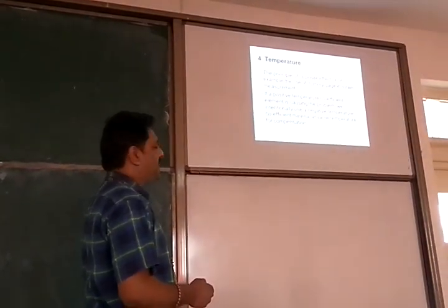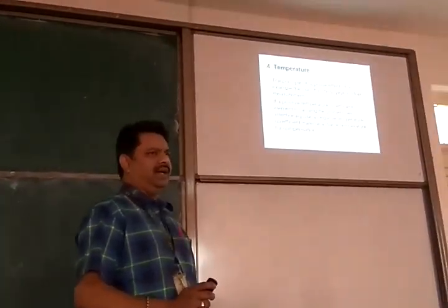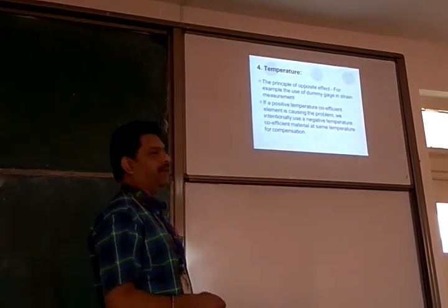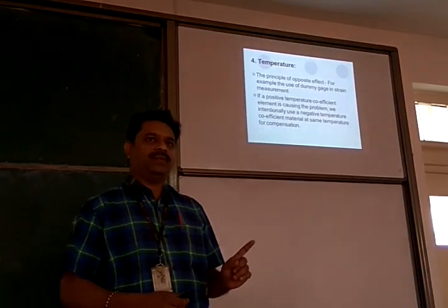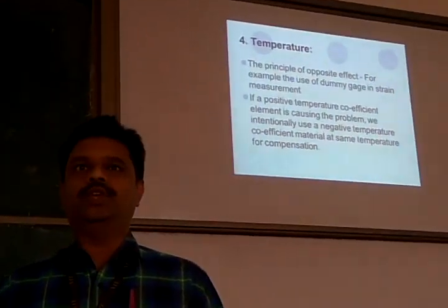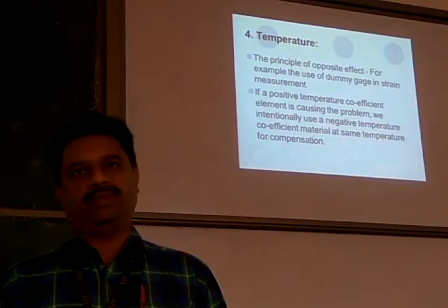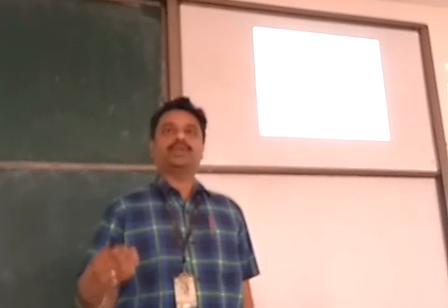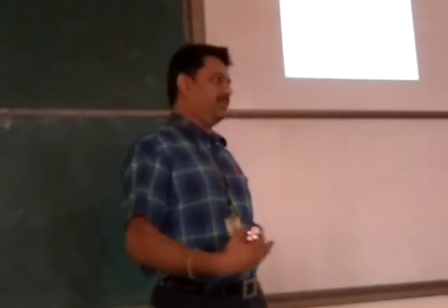And then temperature. In certain problems you can use the principle of opposite effect. Principle of opposite effect means if some positive temperature coefficient material is giving an error, you use some negative temperature coefficient material. Right? Positive temperature coefficient material gives some error, use negative temperature coefficient material.